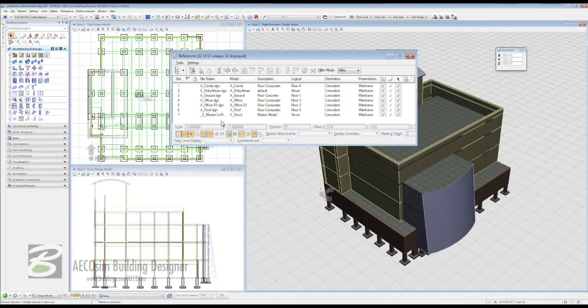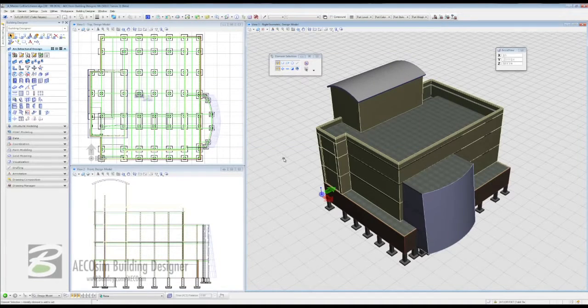And now click OK. And now you can see our structural engineering data, that designs the analysis up to this particular point, has been attached to our design file. And now we can go forward to the next step of creating some construction drawings that include any and all parts of design data. And when our mechanical, our electrical, our fittings, schemes and plans and drawings are coming out, we can attach their models to this particular model to create one conglomerate model for our building information project